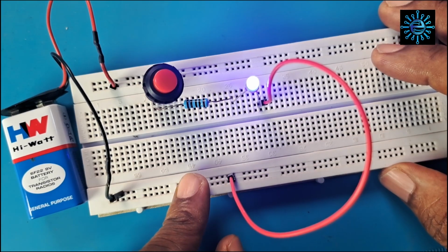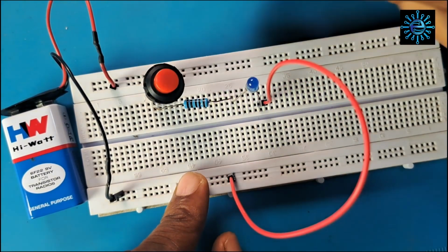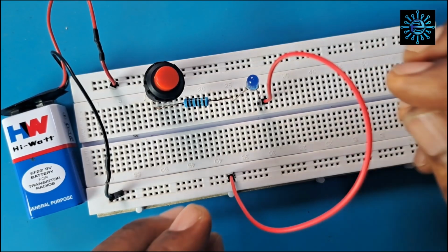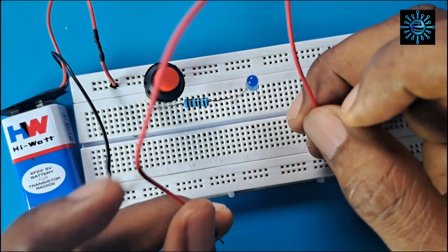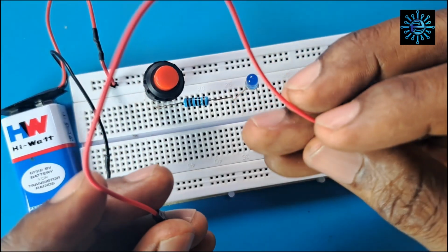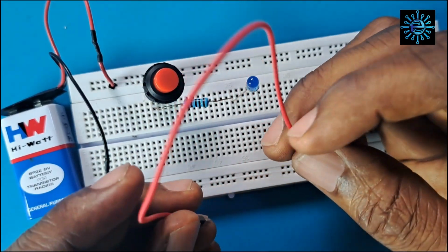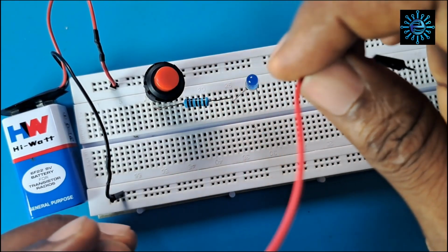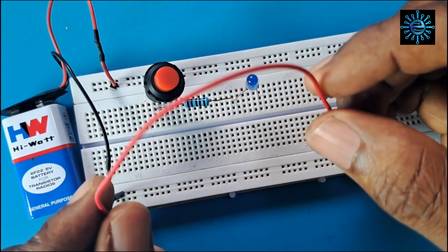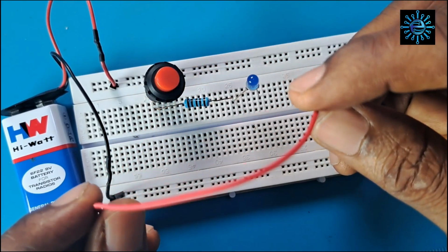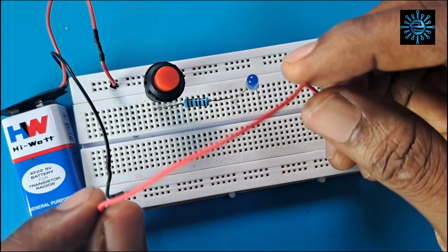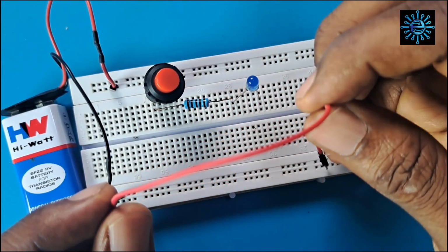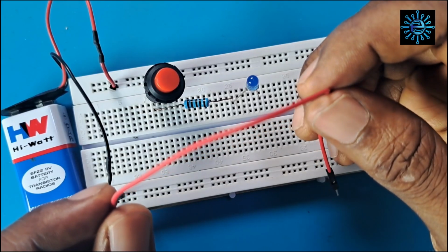Another thing you can do to ascertain whether it can fix your circuit not working is to change the jumper wire. So if the jumper wire you are using is broken inside, it means that current will not return to the battery when you press the switch. It means that that broken jumper wire will create an open circuit in your design. If that is the case, electricity will not see a complete path to flow in the circuit.